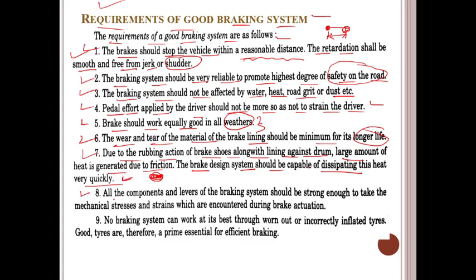Eighth, all the components and levers of the braking system should be strong enough to take the mechanical strains which are encountered during the braking actuations. And ninth, no braking system can work at its best with worn out or incorrectly inflated tires. Good tires, therefore, are prime essentials for efficient braking. So these are the nine points required for a good braking system.